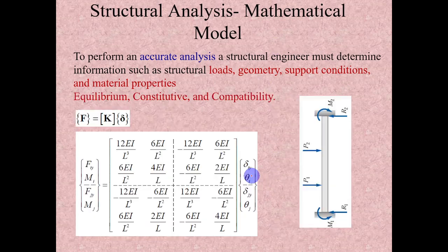In the case of an indeterminate structure like this, where both ends are fixed, the equilibrium equations alone are not sufficient. We need constitutive and compatibility conditions as well to solve this problem. Here, basically, computers are mostly used, and there are n number of ways to solve this problem: moment area method, Conjugate beam method, virtual work method, but this is the stiffness matrix method.